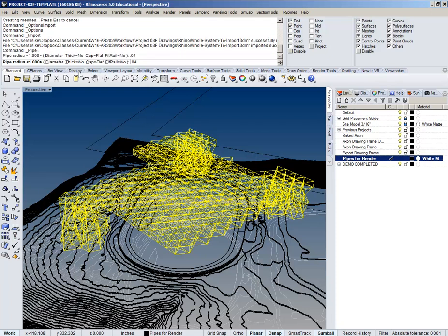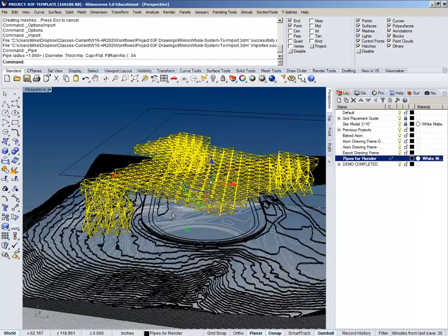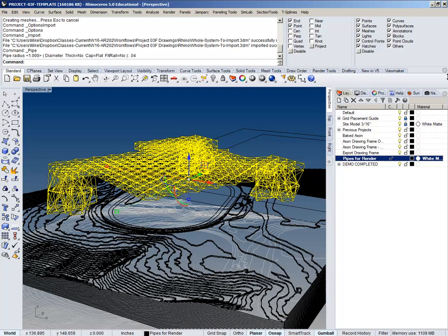And it's a lot of geometry, but because it's so simple, it'll pipe relatively quick. Pipes are extrusions. They don't have as much information as, say, a poly surface does. They basically have a radius, and they have an end condition on them that it's extruded along that. So they're not too heavy lifting. You can see my model's not slowed down or anything.